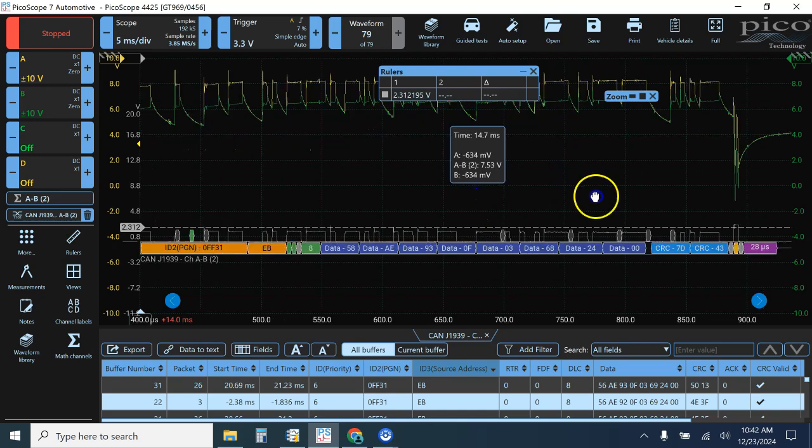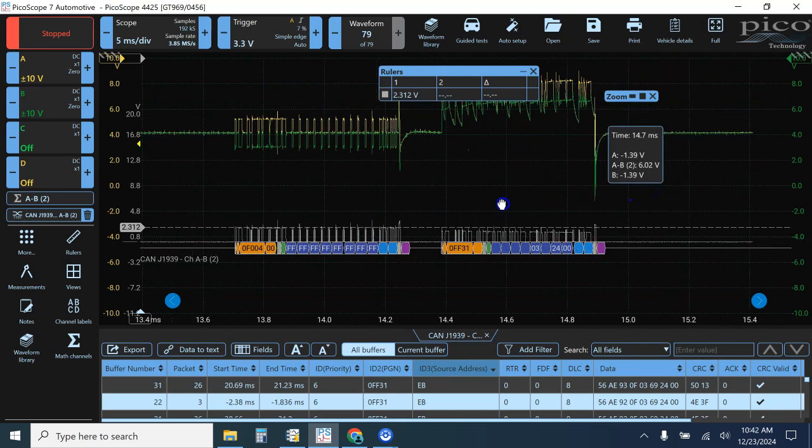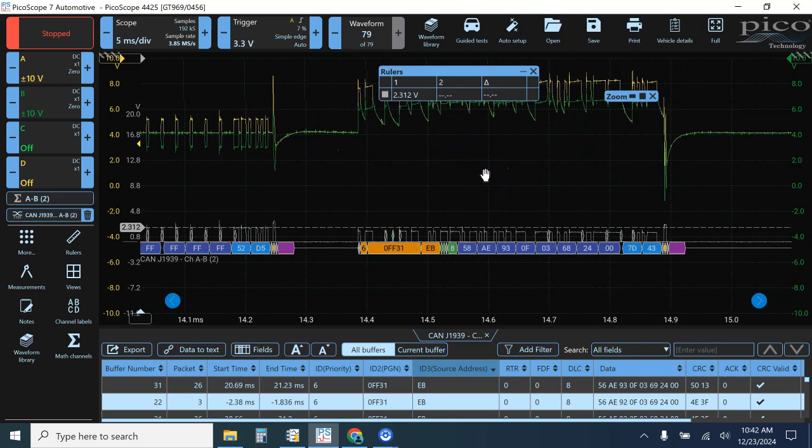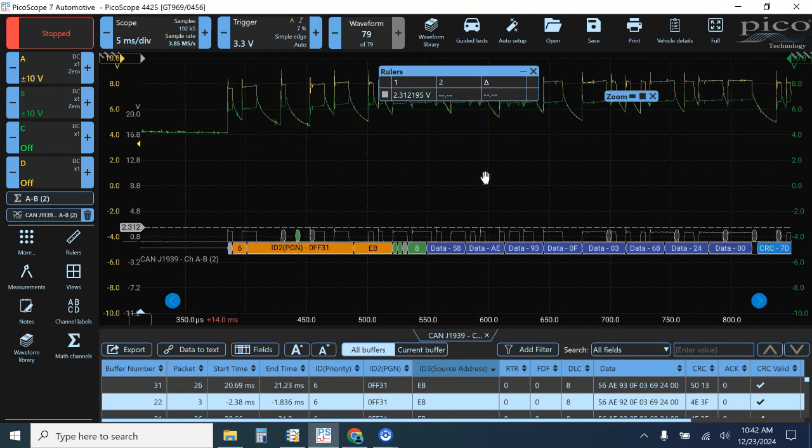We can zoom in here on this one message, which is where you may recognize the problem. This is once again that temperature, pressure, humidity smart sensor. It's easy to get to. I added a couple of 100 ohms of resistance to the ground of this sensor. Because this is a really low power device, it doesn't really drive anything like an output. Putting resistance on the ground of this sensor still permits it to operate as long as it has sufficient voltage to do so. It does, however, as we've seen in other videos, cause an offset of that signal.